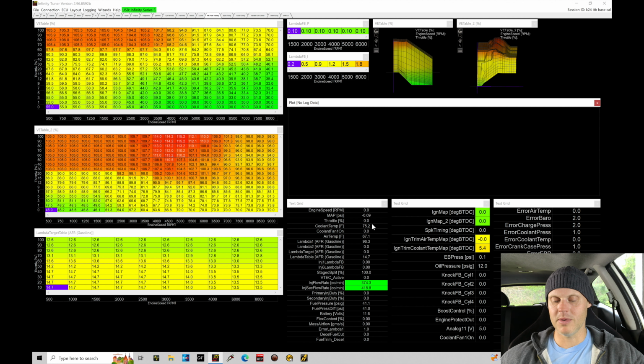Now, what I may be missing here, if I give it some throttle, it's actually not picking up the first bit of travel of my foot movement, which is really important. So right now I'm probably giving it about 5% throttle, and it just starts to pick up right there. So the minimum and maximum positions aren't known properly from the Infinity. Now, this normally would create some problems for us, especially some drivability problems, but in this case, it's going to create major problems because we're an Alpha-N strategy.